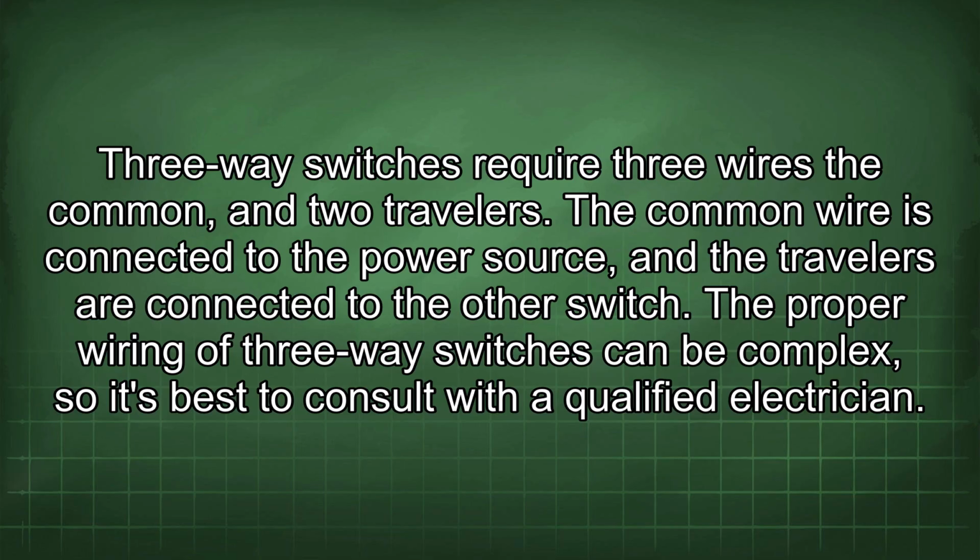Three-way switches require 3 wires: the common, and 2 travelers. The common wire is connected to the power source, and the travelers are connected to the other switch. The proper wiring of three-way switches can be complex, so it's best to consult with a qualified electrician.